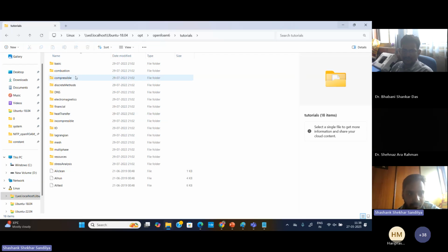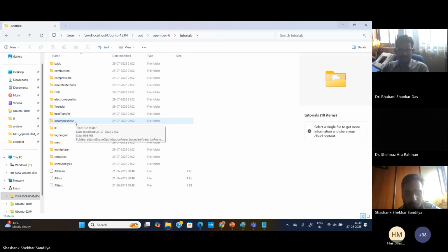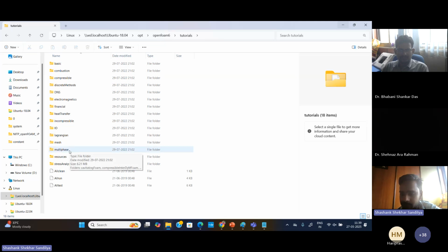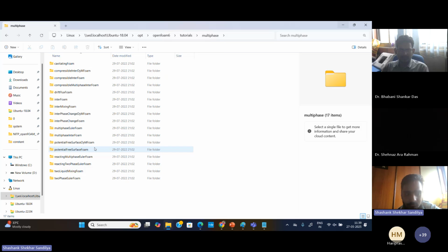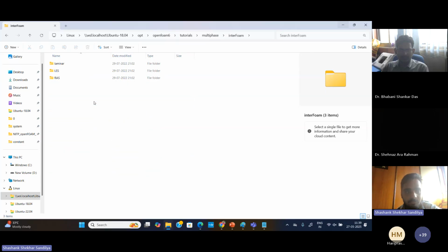In this tutorial, there are tutorials related to various problems like combustion, compressible, financial, heat transfer, incompressible, and multi-phase. So in this tutorial, we are focusing on our multi-phase case, the dam break case, which is a multi-phase problem. When we go through the multi-phase folder, there are lots of solvers. But in this tutorial, we consider the interFoam solver for the study. So we go through this interFoam solver.